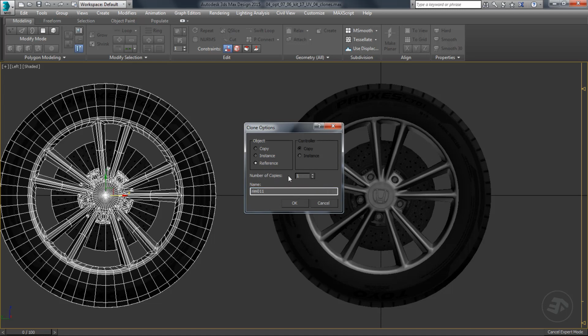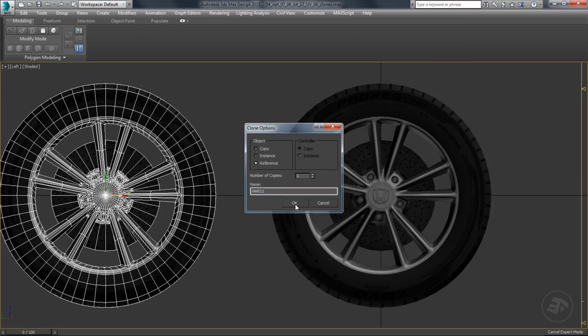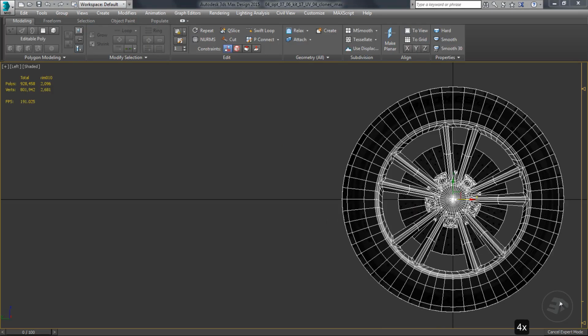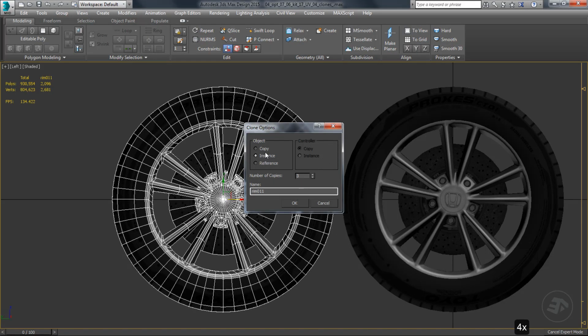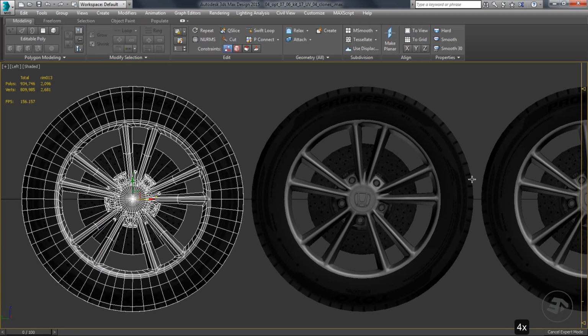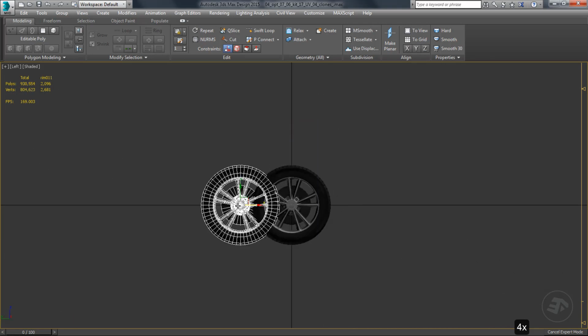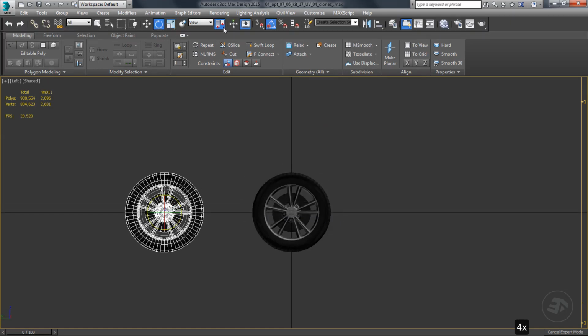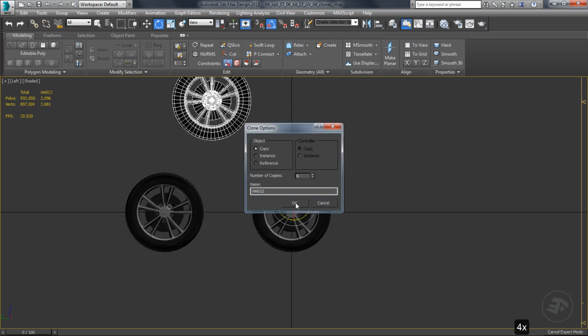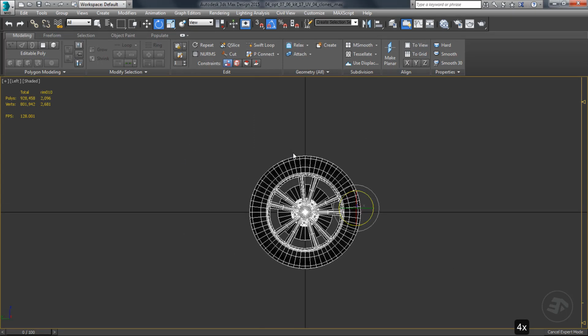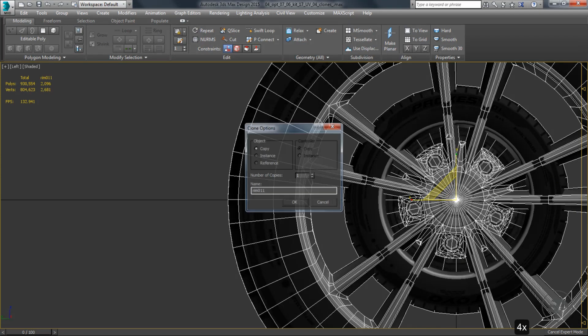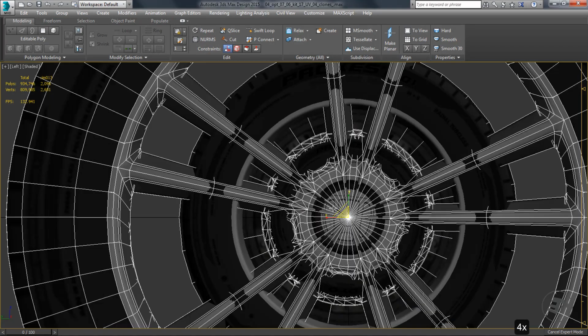If you increase the number of the cloned objects, each cloned object will be separated by the move distance, or the rotation angle, from the original, multiplied by the clone number. The same concepts are also applied when using the Scale tool.